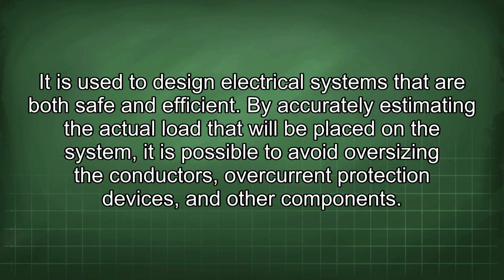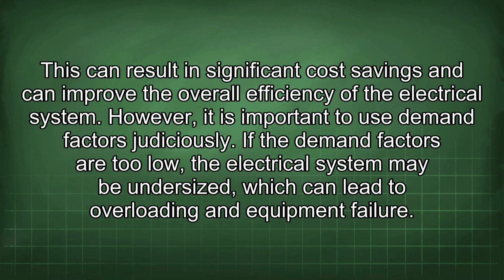By accurately estimating the actual load that will be placed on the system, it is possible to avoid oversizing the conductors, overcurrent protection devices, and other components. This can result in significant cost savings and can improve the overall efficiency of the electrical system. However, it is important to use demand factors judiciously.